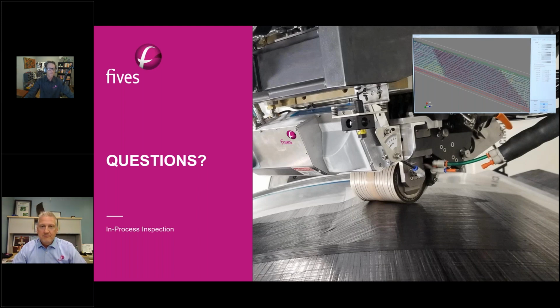Yeah, so to do a good job, you have to know the different constraints, right? Every system, LLT, OCT camera, has what's called a field of view, right? So that's the number of points, or in a camera sense, the number of pixels. And so the horizontal field of view, because that's where we're measuring our profile, right? The sensor's on the back. You have to put yourself on the back of a roller, just like you see in this photo. And so that horizontal resolution is really what you're most interested in.